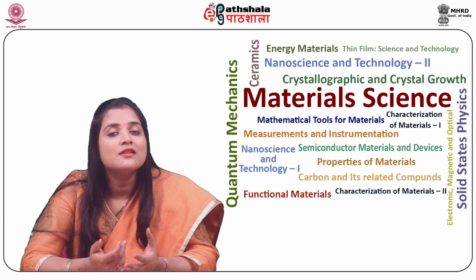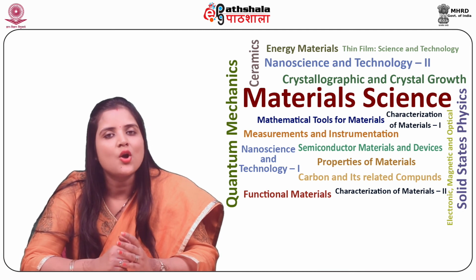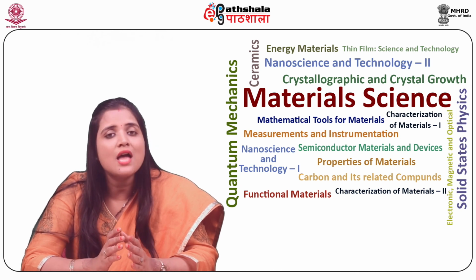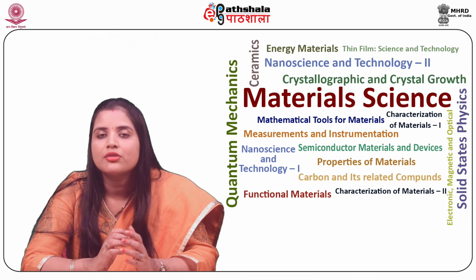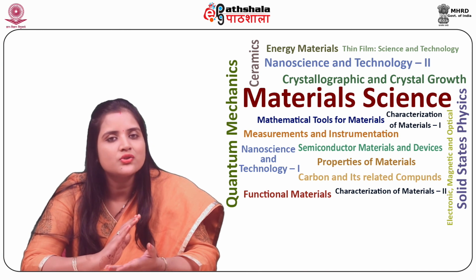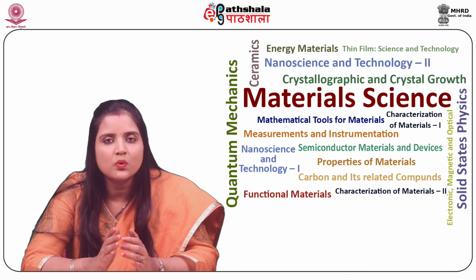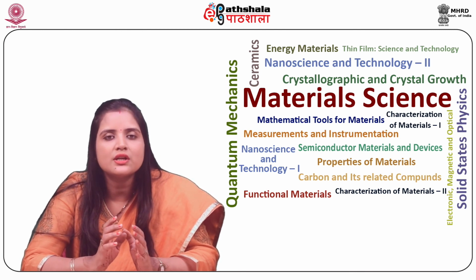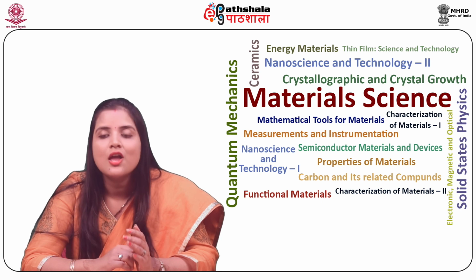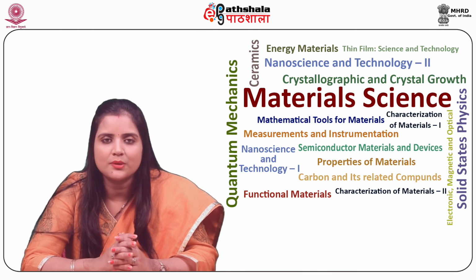We next discuss the merits of electroluminescence. The most important advantage of electroluminescence is the low wattage requirement. Secondly, it has a long life. Then, an external circuit is not required for limiting current, that is, no ballast is required, so it can be plugged straight into the AC power and utilize its intrinsic resistivity to self regulate power. This can be fabricated into flat flexible panels, narrow strings, and other small shapes.